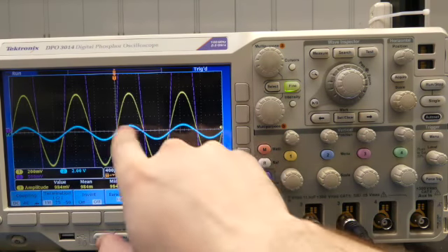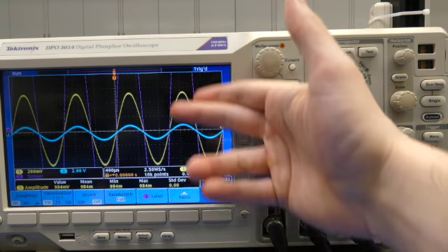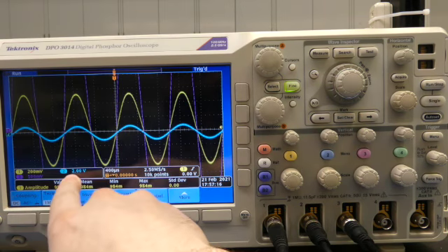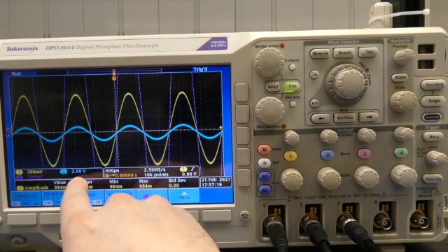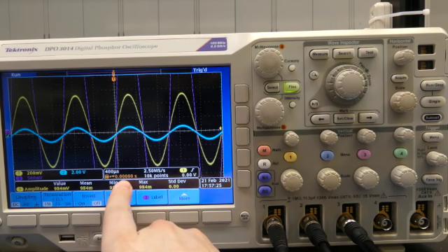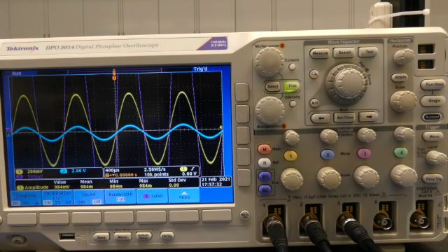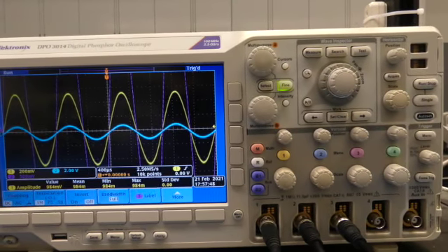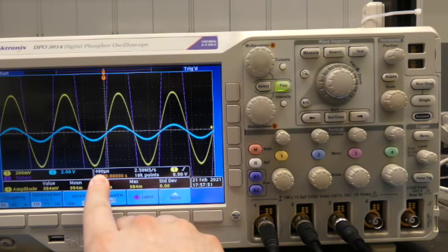Now they're very faint here, but you can kind of see them. There are dotted lines going horizontally across the oscilloscope, as well as vertical lines going vertically across. Each of these are divisions, and these values here tell you what each division means for each channel. Now you can have different divisions for your Y's, but you can't have different divisions for your X's, because everything would start to get all wonky if you start changing your time scaling and having everything set to its own time scale. So we can only alter the scale of the amplitude, or the Y measurement, but for the X measurement, time, those divisions are set by this value right here.